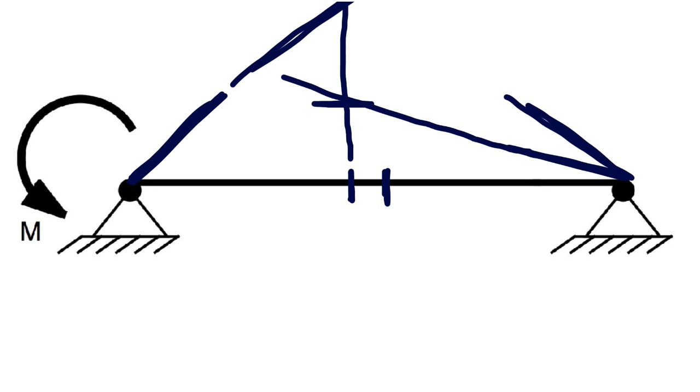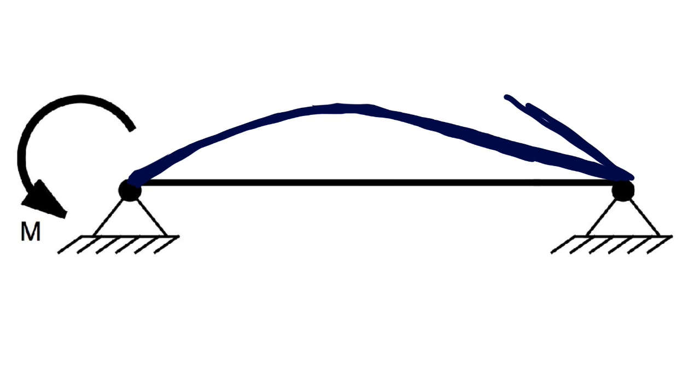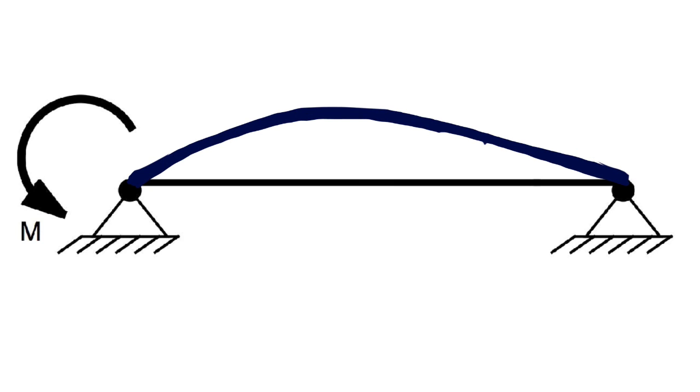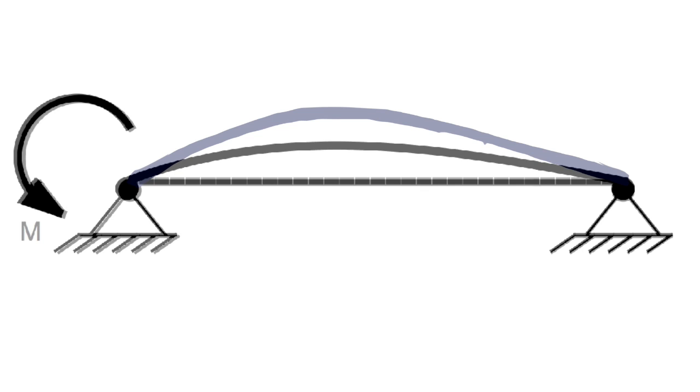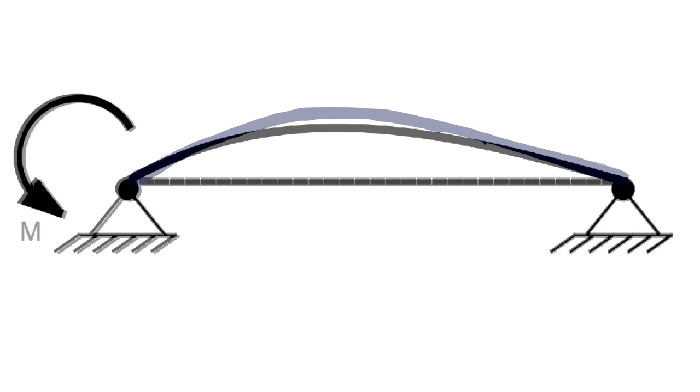So, about half. Now, we draw a rough arc curving downwards, and that is tangent to the stub at the left end, and meets the maximum height line at about the marked location. Finally, we remove or erase the extraneous lines, smooth out our curve to get our deformed shape. Some or all of these steps may be omitted once we get a sufficient familiarity with sketching this shape, but this step-by-step approach makes us aware of all the salient details of the beam or column's deformation. And now we compare with the theoretical shape.